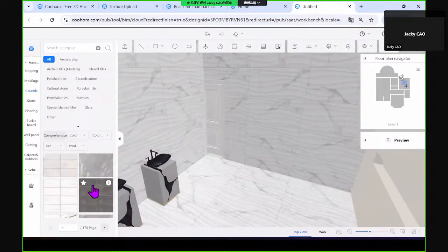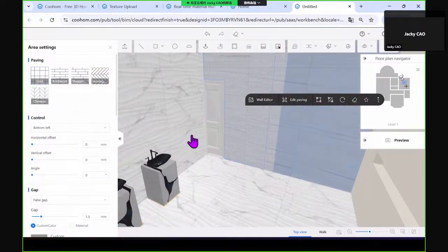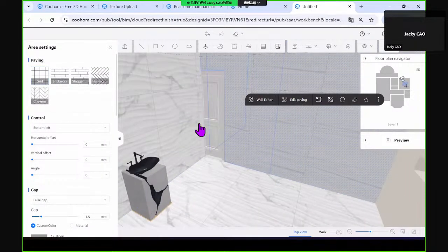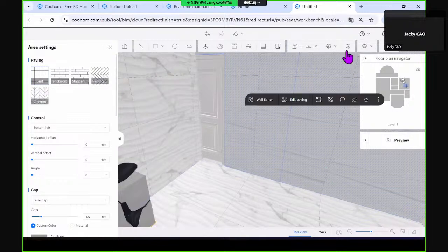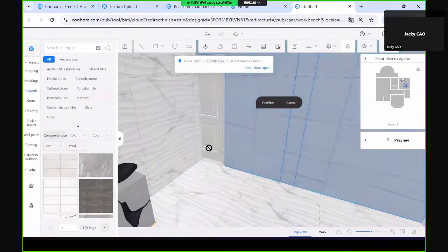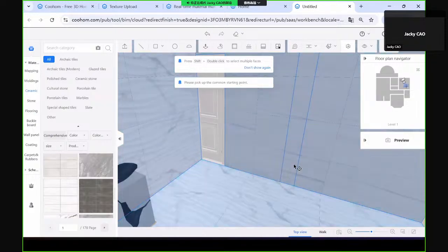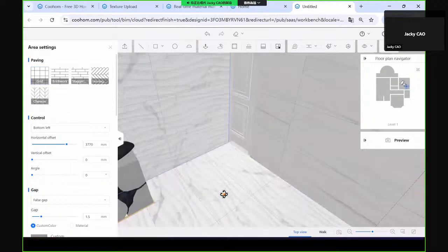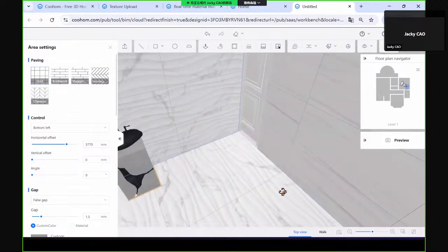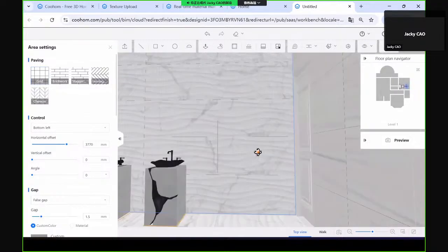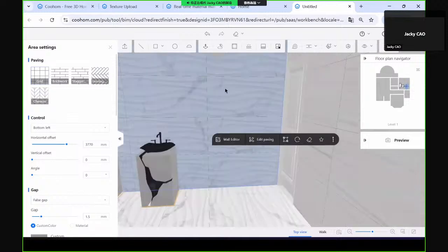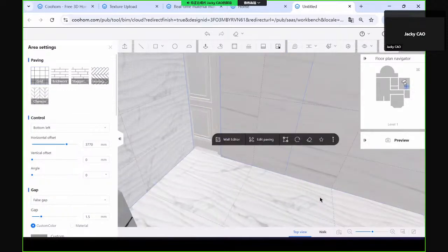But if you need to control the different positions and different gaps, you can use this function, align in multi-planes. Just click the correct position, and then give a proper starting point and end point. You see all the sides connected, and the gap continues.